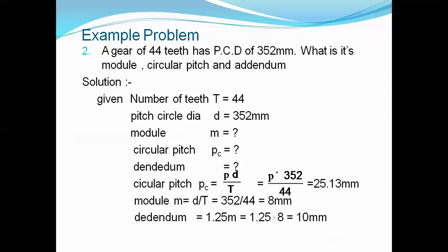Next, addendum is 1.25 into M, 1.25 into 8. Since module is the reciprocal, we took it that way. Okay, so with this I conclude today's session.